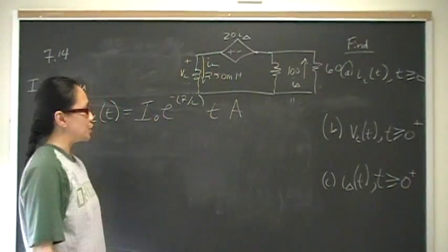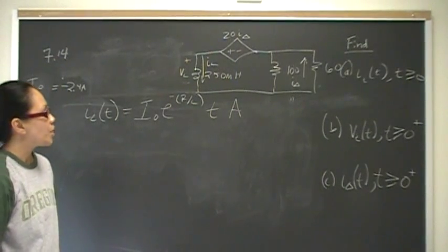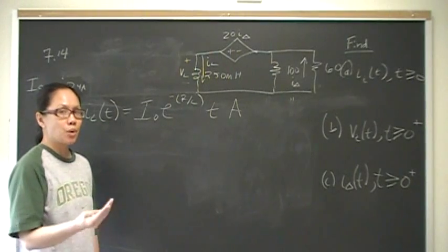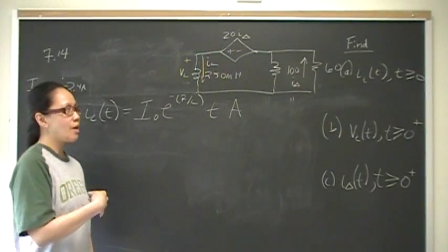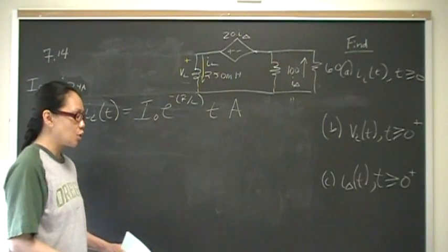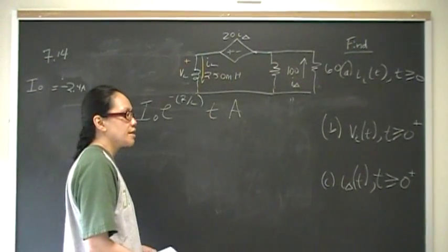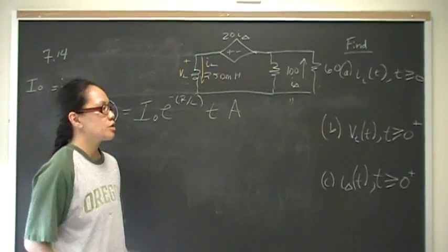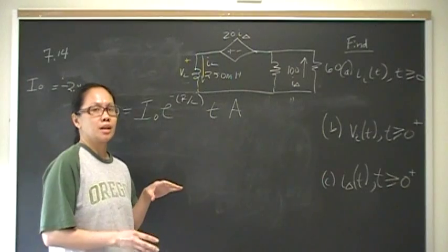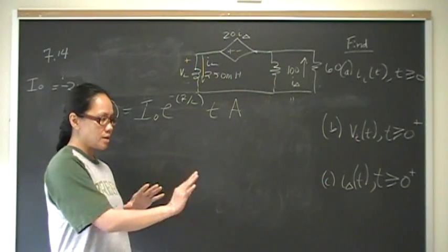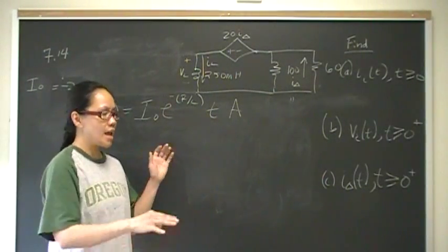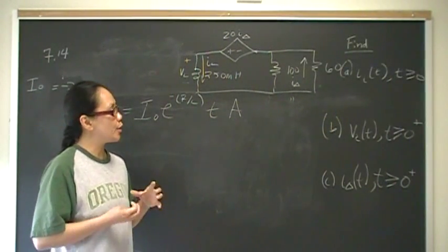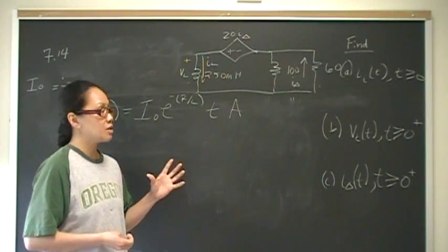So what we have to do is draw back on chapter 3 or 4, where we learned about Thevenin equivalence, because the Thevenin resistance is found when we open the load. We open the element we're interested in, and then no matter how many circuit elements there are, we ask what is the single resistance seen by the load?